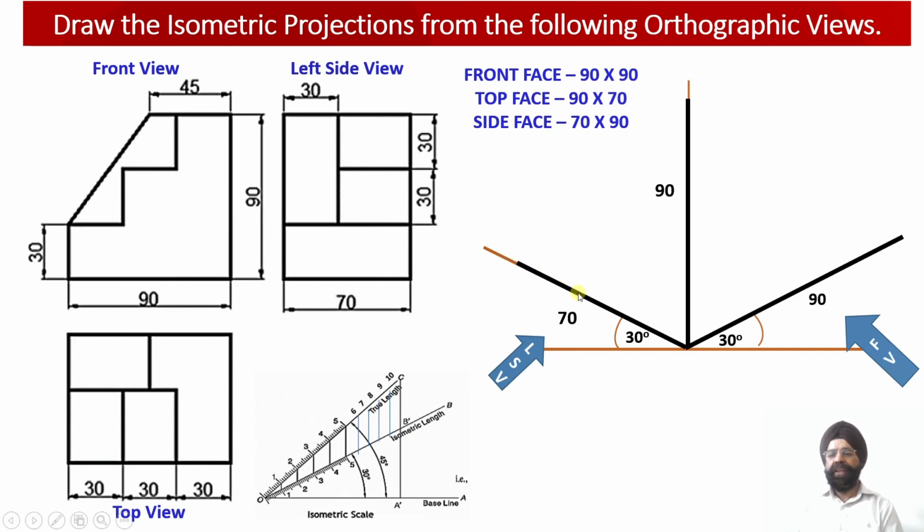So within this XY plane, we have to draw the left hand side view face, whereas the front view face of this isometric construction will be drawn in the YZ plane. So this is the y-axis and this is the z-axis, right? And accordingly the top face of the solid will be constructed. Now let us work out this particular geometric construction.